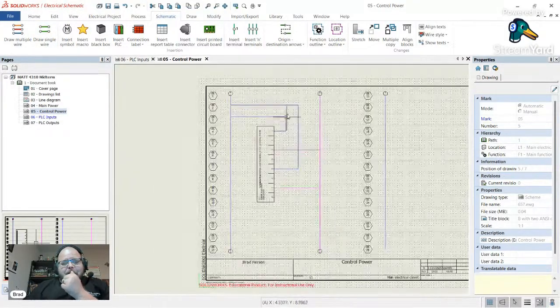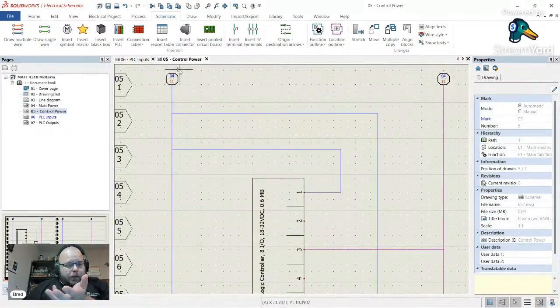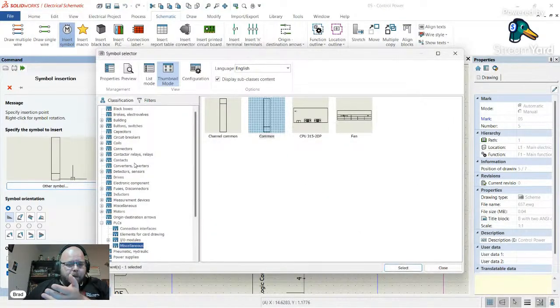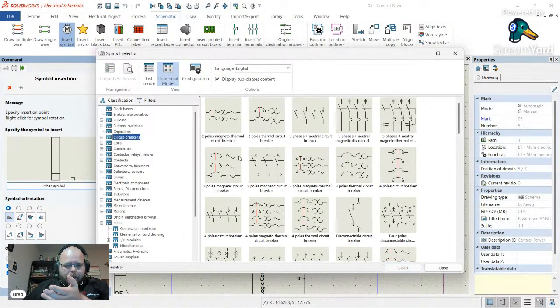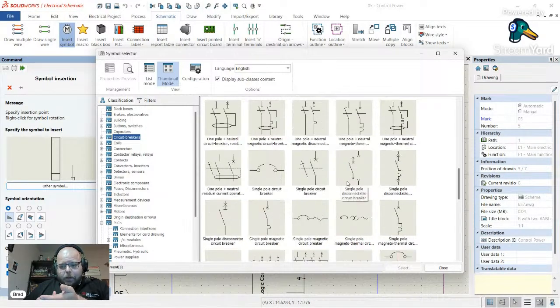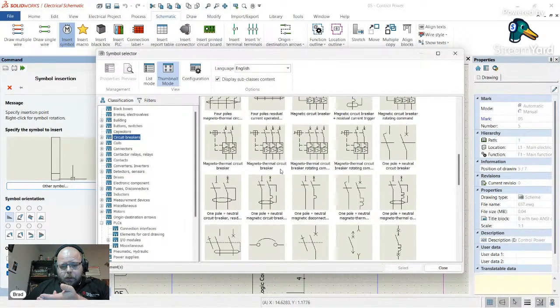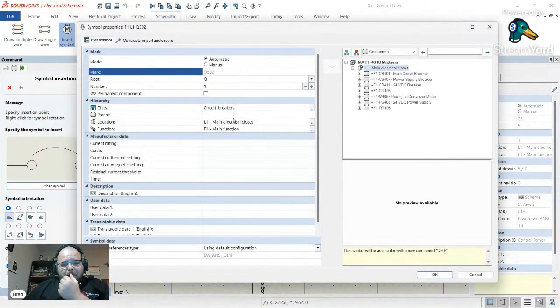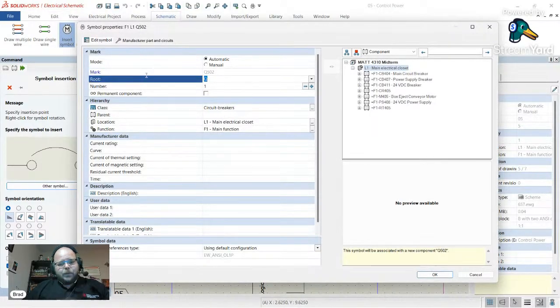So, now I would protect those. I am going to drop in a circuit breaker on both. And this is a thing, again, it's not in the bill of materials, it's not in the assignment description, but you cannot overprotect these devices. I don't remember what they draw. Honestly, not a ton. There's not a ton of draw on the individual, but I am going to protect them.